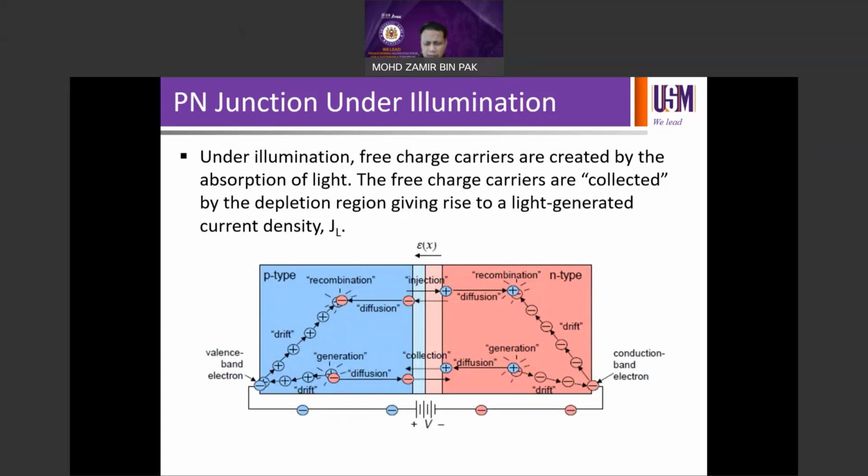But when you talk about low injection level, for example, in the range of 10 to the 12, when you're talking about your silicon with, say, p-type of 10 to the 19, obviously you won't be able to see any change when you compare your minority carrier at 10 to the 12, sorry, the injection level at 10 to the 12, with 10 to the 19 of your doping level, right? So 10 to the 12 will just be negligible.